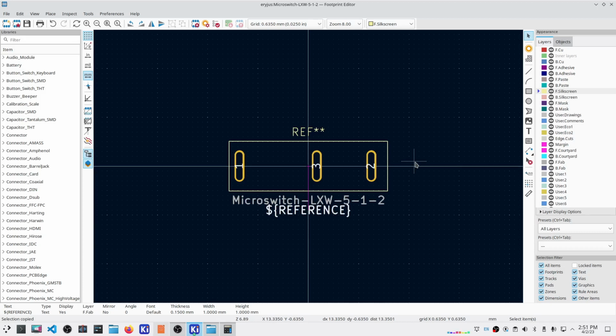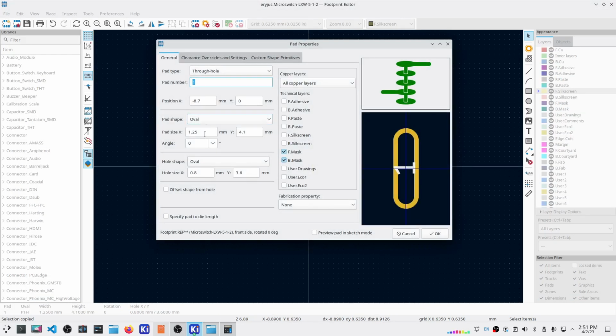Now, my challenge is that the holes or these spades are not rounded, they are rectangular. So let's change that. So the hole shape has to be oval, so that means I have to extend it. It's oval, which means I've got half a circle on each end. The radius of that circle is 0.4 millimeters. If I take 0.4 millimeters off of each end of the slot, I end up with removing 0.8 millimeters. That's 2.8 millimeters long. That's too short. So I really need to add 3.4 plus 0.8. So that's going to be 4.2 millimeters long.